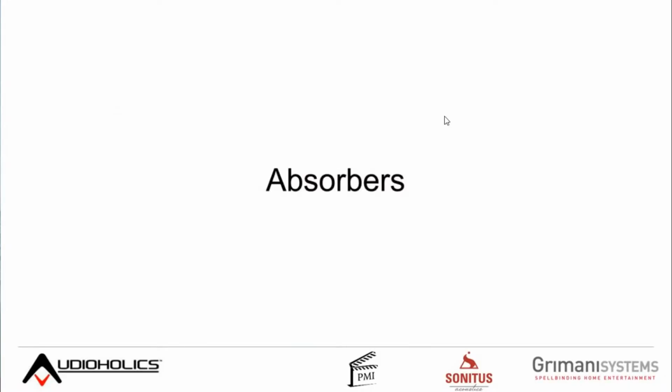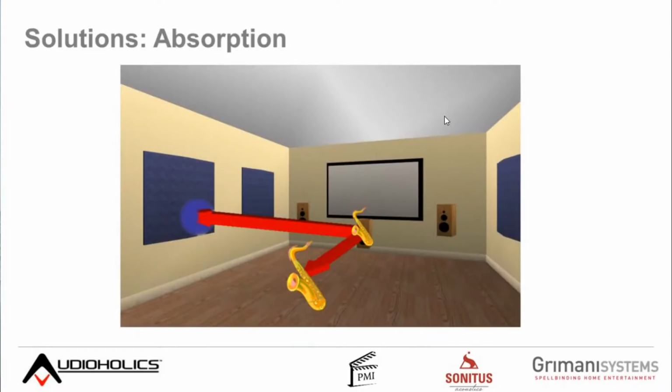Let's talk about absorbers. So what does an absorber do? It essentially is a device that turns the impinging sound that hits it into something different. The typical absorbers are actually frictional. They're usually a thickness of fiberglass or rock wool. And I thought I actually had brought a piece of raw absorption home, and I did not. Okay, sorry, my bad. But basically, think of a big chunk of either foam or fiberglass. The waves that hit it actually friction inside the little particles and turn into heat. So absorbers convert sound into heat.